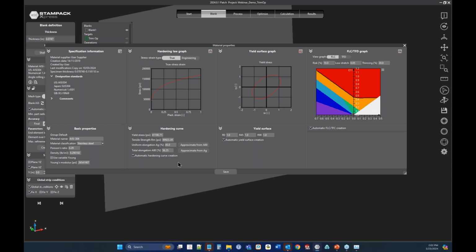Next question is, does the software work well for deep draw operations, and can it simulate breakaway on trimming operations? So deep draw and breakaway on trimming. It's exceptional for deep drawn parts. As far as the break, it does not calculate the break in the thickness of the part. But for deep draw, as Luca says, it's home game. It's really, really well suited to ironing and the thinning that goes on in a deep drawn part. That's one of the biggest pluses with Solid.